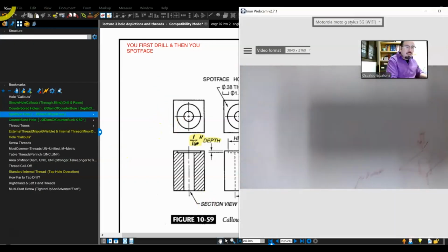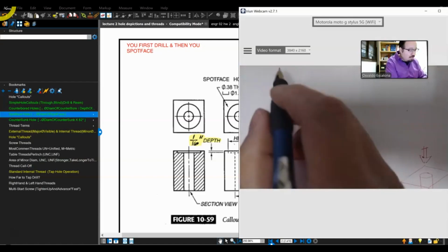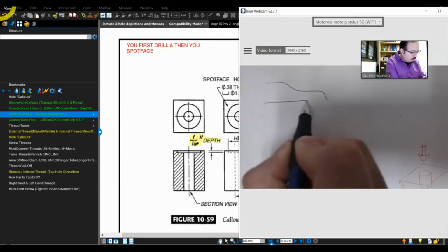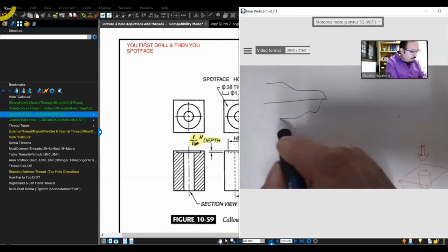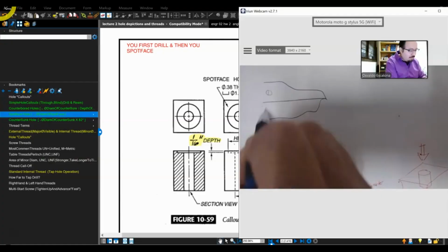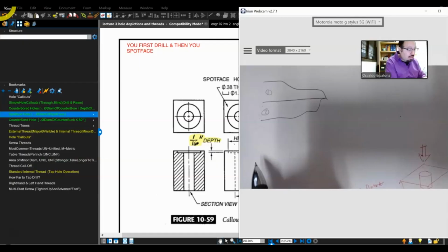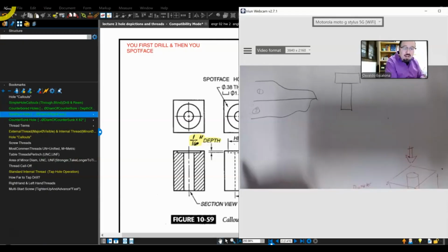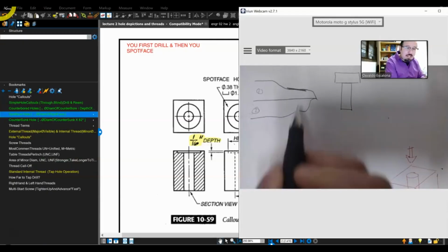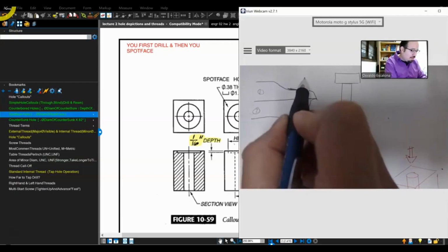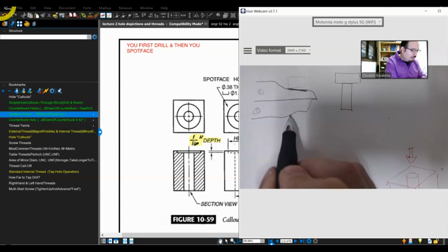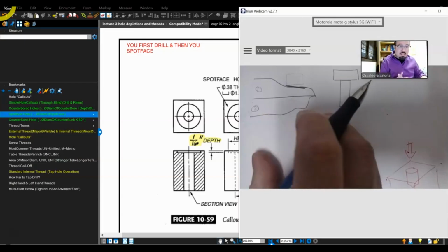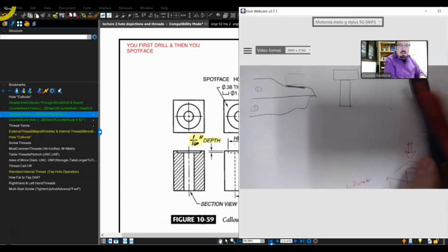Okay. There are going to be situations where you're going to have parts that are really complex. Let's say that I have a part that looks like, I don't know, like that. And then I have another part that looks like this, right? So one part on the top and one part on the bottom. And you want to make sure that you can put a bolt, put a bolt like that, right? And you're like, oh shoot, man, that thing is curvy, right? So if I want to put it, my bolt is not going to sit correctly, right? The same thing is going to happen to the bolt. If I want to put a nut, the nut is not going to sit correctly. So what you actually do is say, you know what, I need to make sure the thing is flush. So I am going to create a spot face.